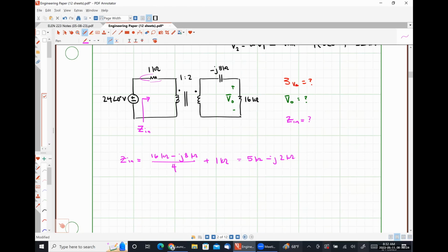So let's take a crack at the complex power here. Actually, I'm going to make one very slight change just so we don't have to do any extra math. I'm going to call that an RMS voltage so we can be lazy and not have to remember that factor of 1/2 that we would have needed if I didn't do that. So, all right. I'm trying to find the complex power supplied by my voltage source. What 2 pieces of information do I need? Voltage and current, right? Well, realistically, actually, I don't even need the current anymore, although we could easily find it. That's what my initial thought was, just find the current, but we could actually just use that input impedance as well, right?